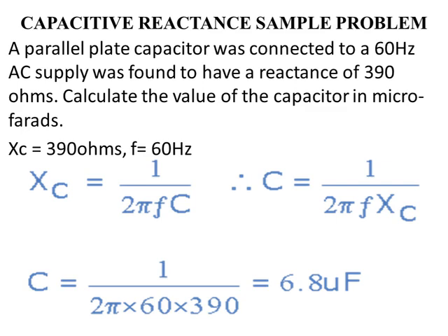By the time you do the division, you'll be getting 0.000068006. Since our answer is said to be in microfarad, you take that times 10 to the power minus 6, and remember that 10 to the power minus 6 is micro. So instead of writing 6.8 times 10 to the power minus 6 farad, you just say 6.8 microfarad. Can you see? Just very straightforward. Just make sure that you punch your calculator accurately.